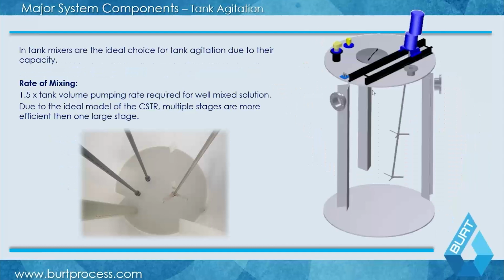Taking a look inside the tank, you see the cutaway here. This is what I was referring to a moment ago. You have your waste which comes in and flows down right into your mixer backwash here. Not shown, but this is your chemical injection ports which follow down. So essentially you're putting in your chemistry right where you have your waste coming in directly into the mixer backwash in this case. What that allows you to do is avoid what's referred to as short circuiting your tank. When you short circuit your tank, what that means is the waste comes in and goes right out the effluent. It basically is not mixing the solution.